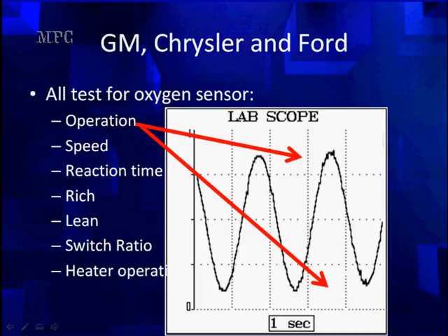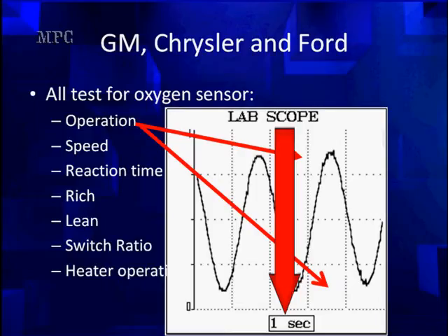When we talk about the signature analysis, we're going to be using a digital storage scope like you see here. Let's take 1 minute to talk about the setup on this digital storage scope. Across the bottom, you see 1 second. That means we're looking at 1 second per division, and in all of our scopes, we're going to have 1 second. In this particular case, it's a 5-second window.